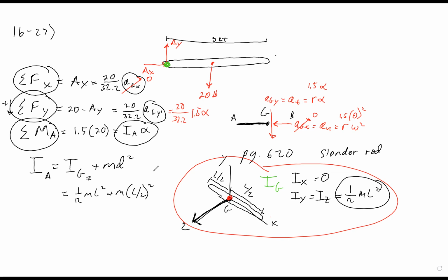What is this? This is shifting our rotational inertia away from G to another location. The location is whatever the distance is from G, and that's what this d is. What is d equal to in the example on page 272? It's equal to half the length of the rod. Then they finish adding in the values, so try not to get too distracted here.